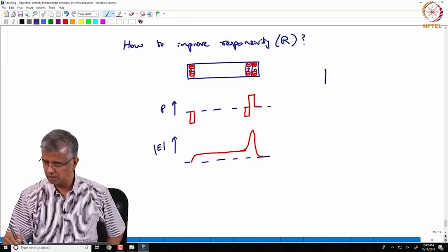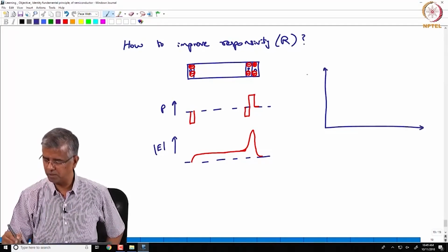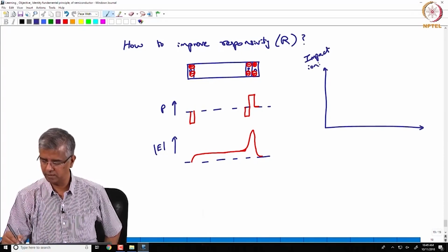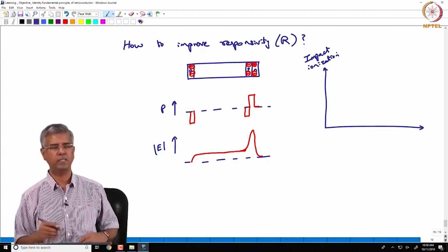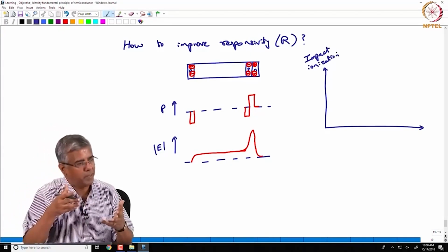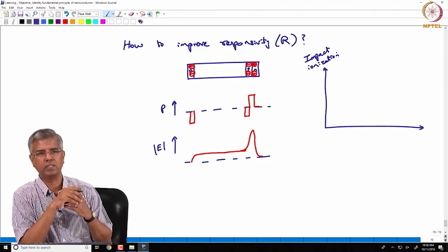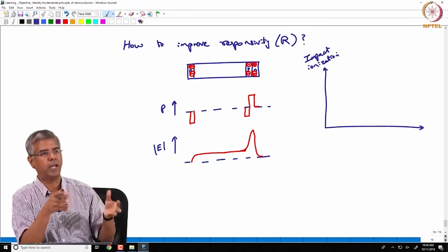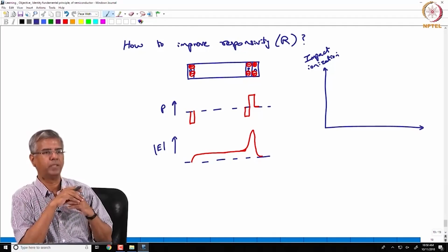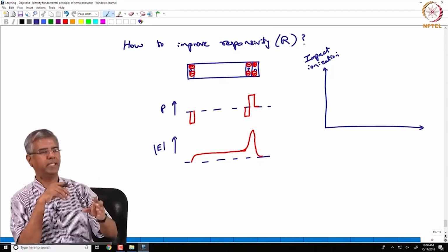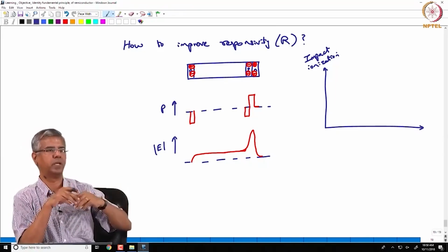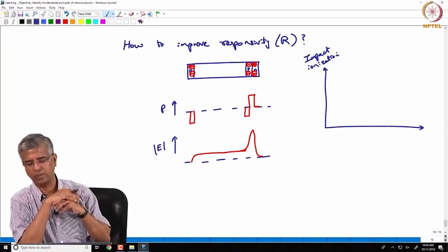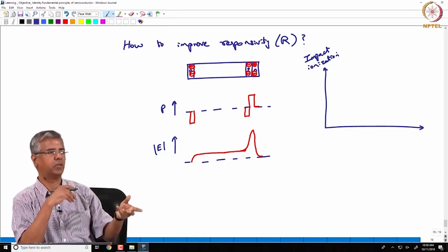Under those conditions, you have a process that's called impact ionization. Basically, these charges have so much momentum, they are traveling at such a high velocity, that if they collide with any other nearby atom, they are going to just hit it and ionize that atom. So they are going to immediately have an electron pop off from that location, and you generate an electron hole pair.